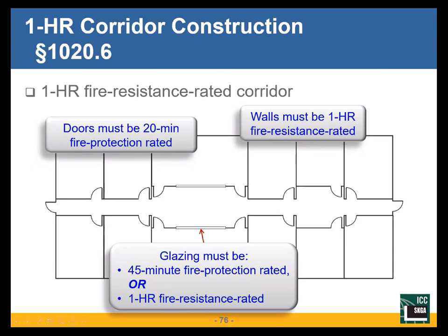unlimited in size. In addition to that, all of my ductwork penetrating that corridor, penetrating this 1 hour fire resistance, has to have a damper in it, a fire smoke damper. If it's in the ceiling, I've got a corridor damper or a ceiling damper. That's appropriate. There's a lot of requirements that when you say, oh, we don't need a 1 hour corridor, there's a lot of things that fall away when the 1 hour corridor is gone.